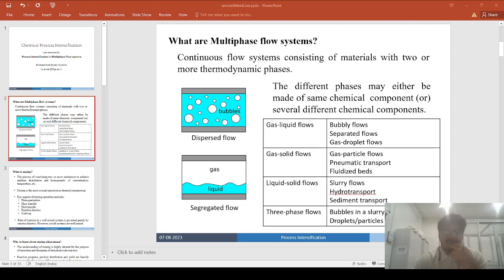Now, for the case of the compact heat exchanger, by reducing the channel size or using a micro channel, you might generate a lot of high power as compared to the conventional heat exchanger. And in the case of foam heat exchanger, you perform surface enhancement by metal coated polymer foam for micro power generation. Now in the case of the inverse flow reactor, the mechanism used based on the multi-phase flow system is to increase the residence time and better phase mixing.